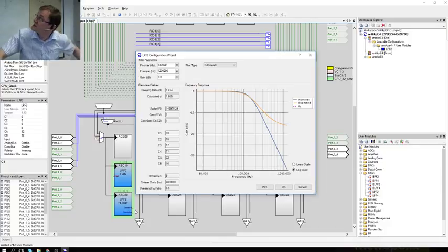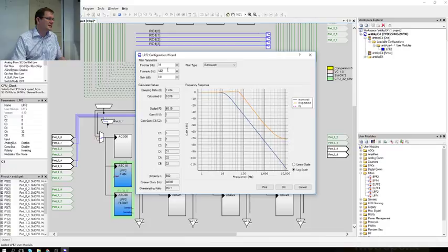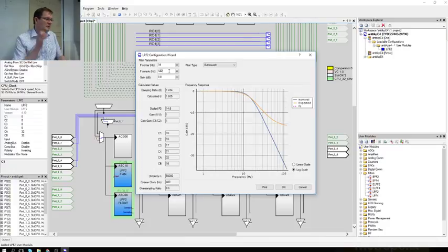There. Doesn't it look much better? And we basically are shooting for a corner frequency of about 10 hertz. How to do it? Basically, you go and start reducing these. Let's see. Does it go to that one? Yeah, it actually does. That's nice. So now I got 14 hertz as the corner frequency.